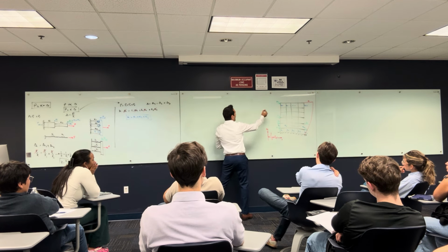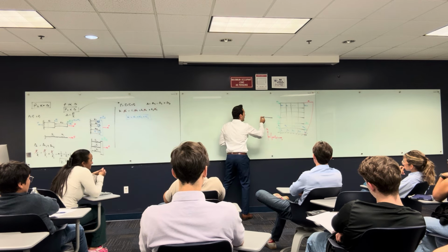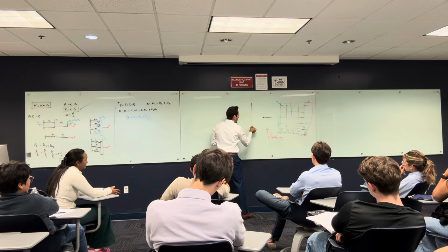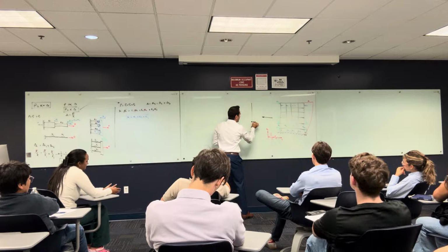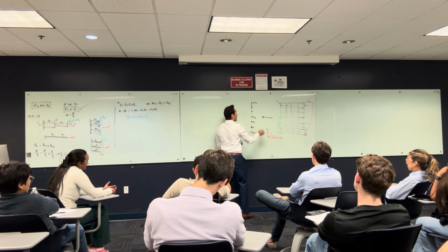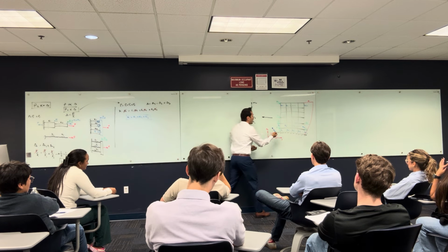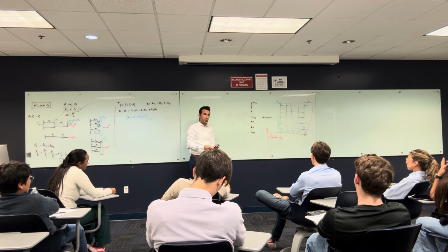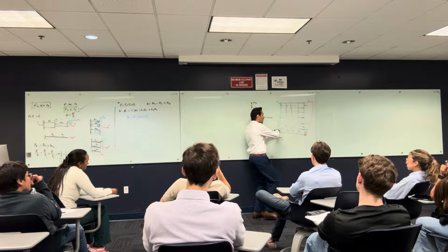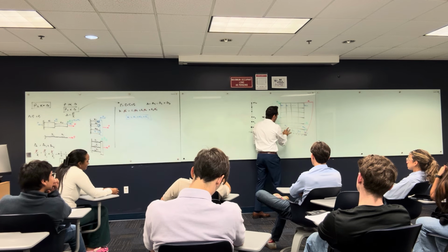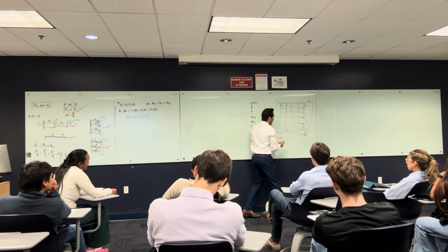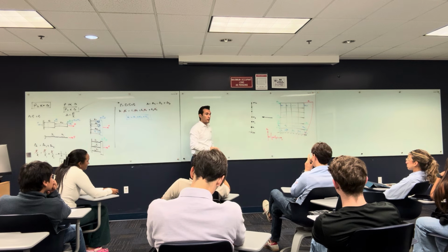So what I can do here is convert this 3D system to a multi-degree of freedom system, something like this, where I have a mass m of story number 1, m of story number 2, m of story number 3, and I keep going up until m of story number n. I can get the equivalent stiffness of each story, because all the columns and shear walls I can sum. By the way, this is not axial stiffness, this is shear stiffness. If you want to make it with a spring, you can represent it by something like that. This is how the spring looks.